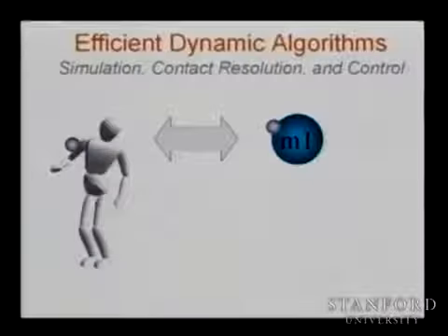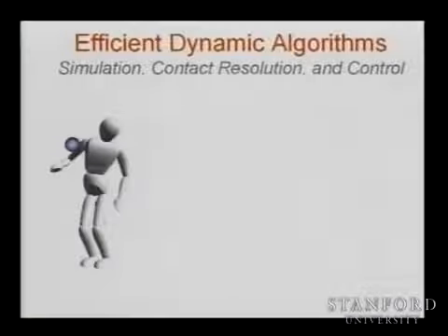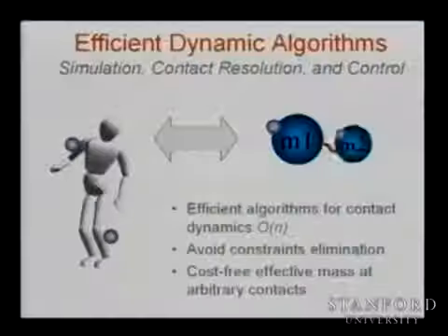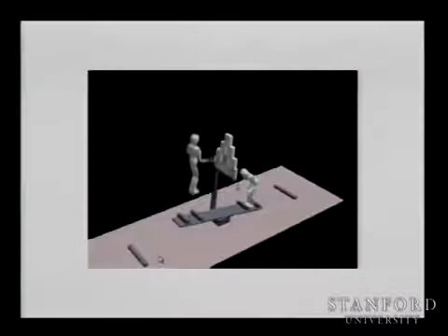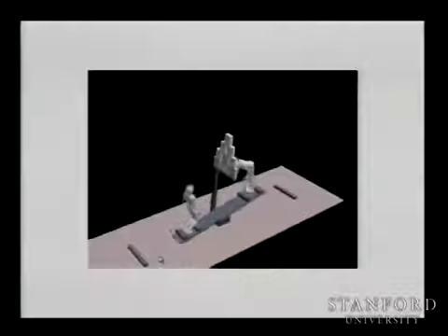But here, we are able to reduce the problem to this, because we can use the mass matrix in this direction. We can use the effective inertia directly. The collision doesn't care about what humanoid robot you have. You just need to know what mass properties you have at the contact. So with this, we have a very effective algorithm that allows us to simulate and resolve collision in real time.